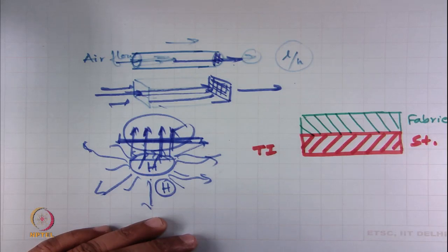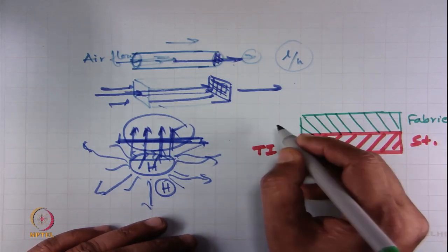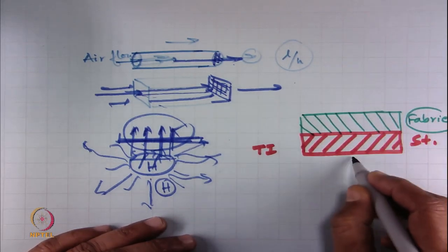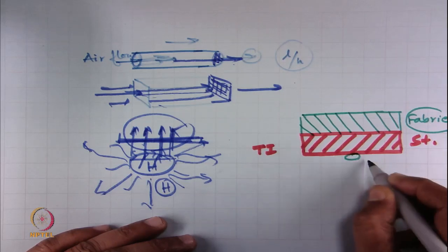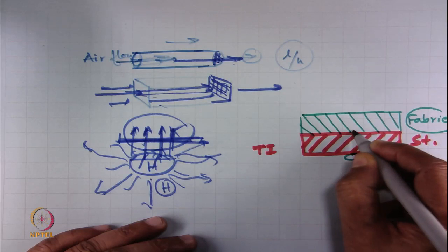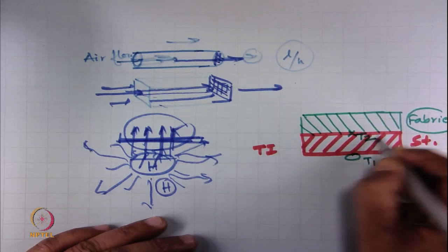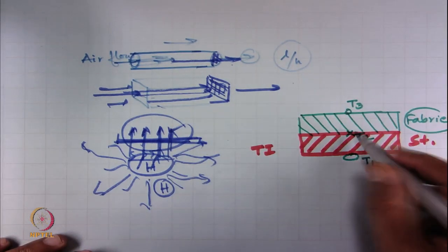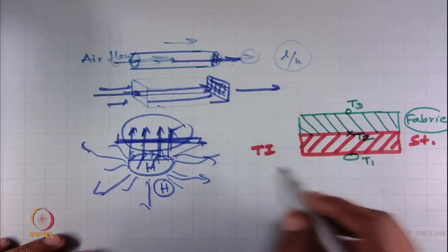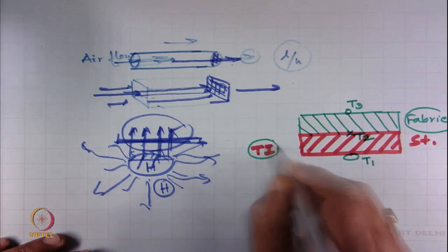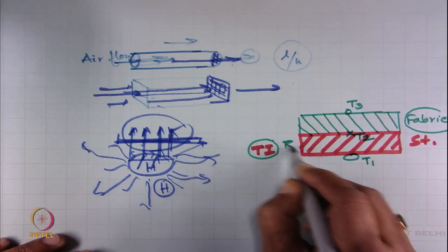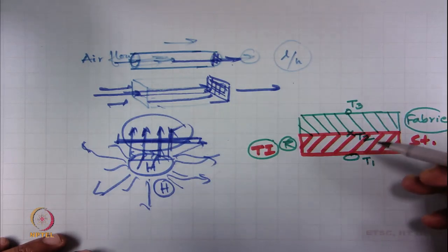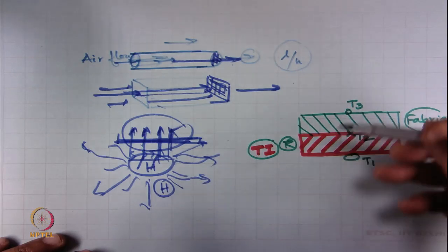If we want to measure the thermal insulation of this fabric, we have to measure the temperature at junction points T1, T2 and T3. The ratio of the temperature difference between the surfaces to the thermal resistance is constant when the materials are in series.